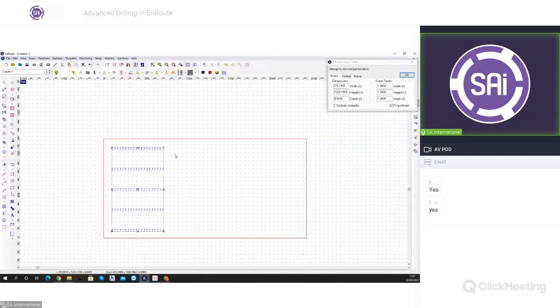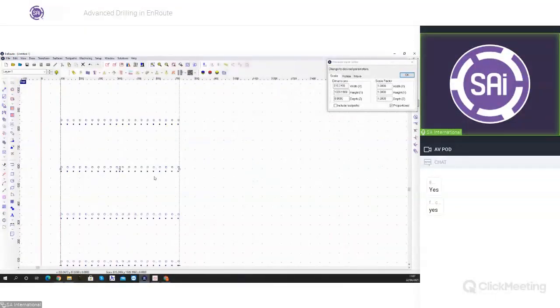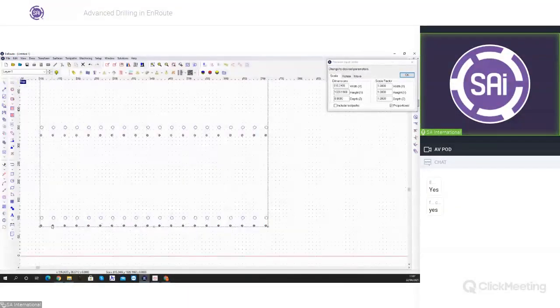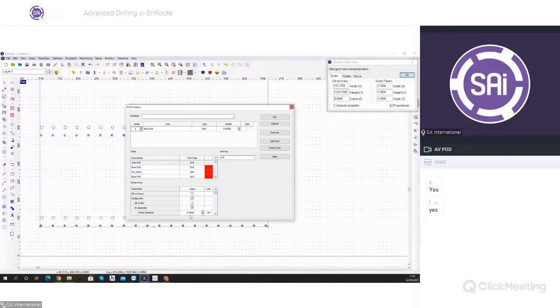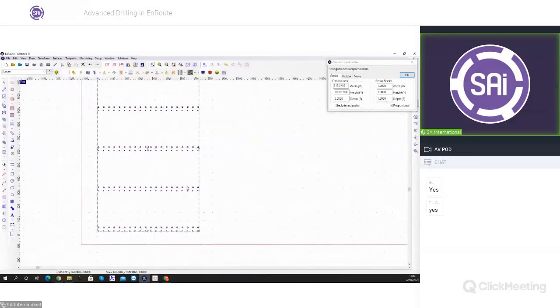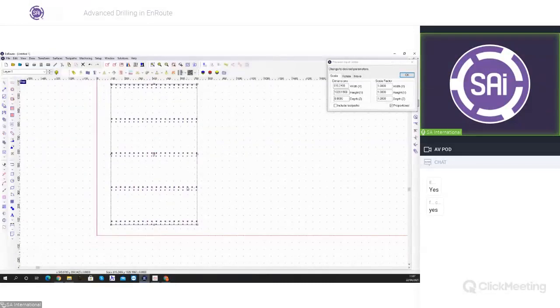And then when we hit apply, as you can see, it will only have applied them to these 5 millimeter holes. And of course, we can then also do the same. I'll just go to 8 and then set this to 8. And that way, when you receive a DXF that has no layers, you can quite quickly process those drill holes as well.